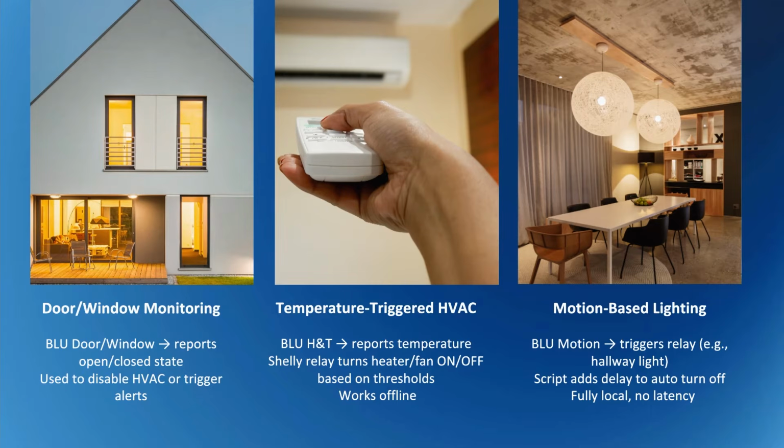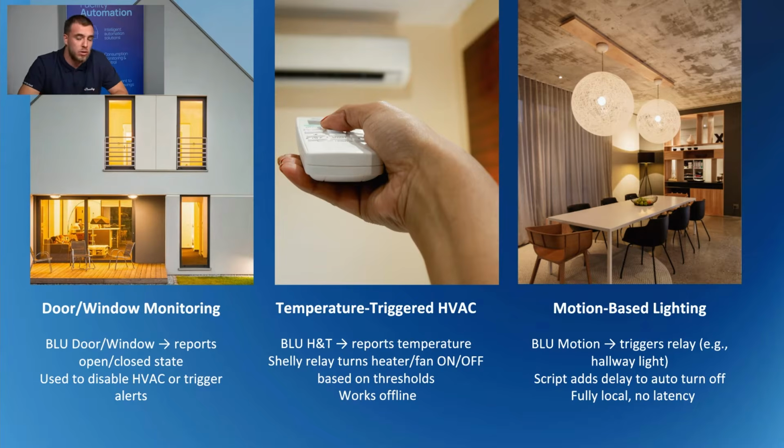So here I also gave you another example of temperature triggered heating, ventilation, and climate control, as well as motion-based lighting. This is something very classic. As you know, let's say you have a Shelly Blue Motion. You add it as a BTHome component in your Shelly gateway device, and you set up a very simple action which turns on the light. And if you want, of course, you can complicate it a bit more and add a custom script which turns on the light and later on turns it off with a timer which is in the script itself. We prepared a simple script to show you that.